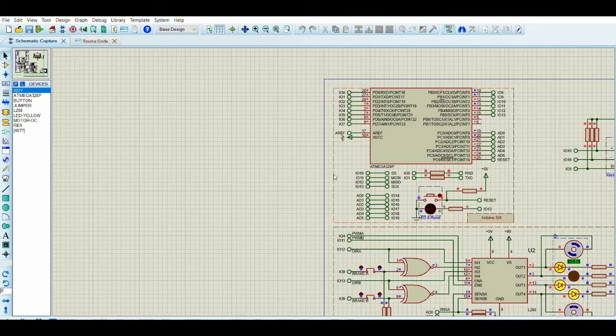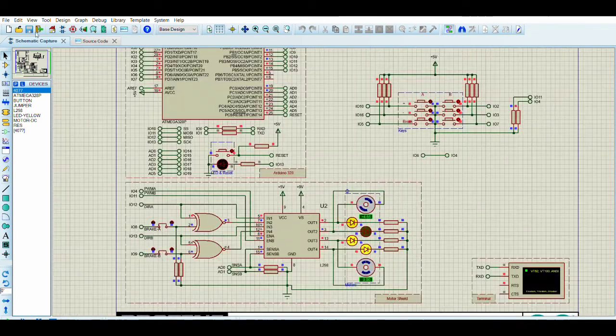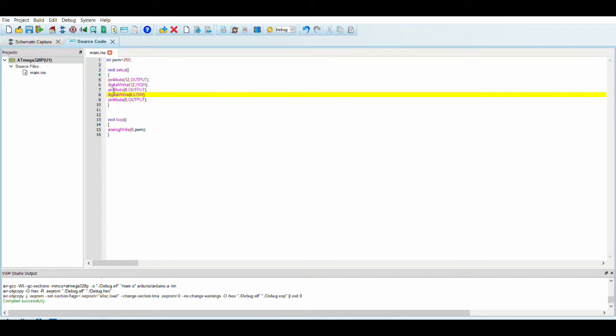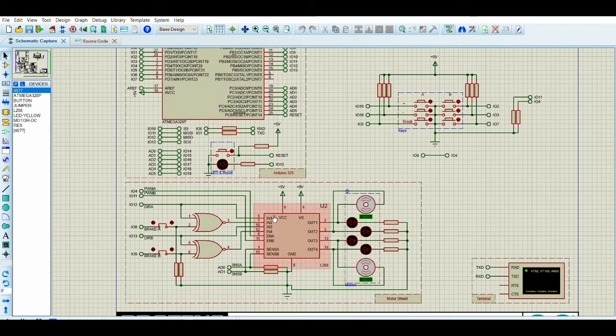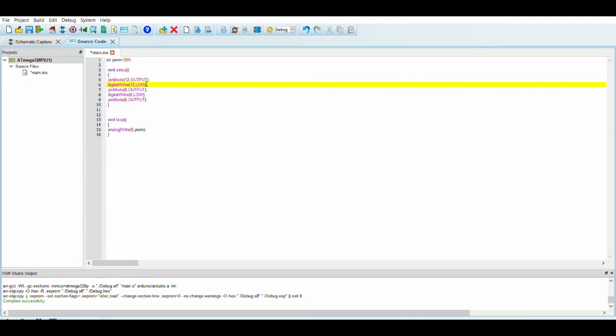Now let us try to run the motor anti-clockwise. For that we first have to pause this, and for anti-clockwise rotation, we need to set IO12 at low and IO8 high. So here we need 1 at input 2, and let the input at pin 12 be low.